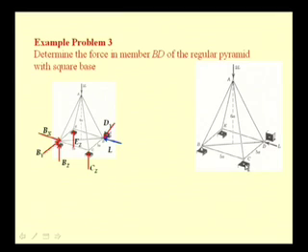And at C we have a slender vertical rod, thereby the member can only support a vertical reaction and thus offers only a vertical component of reaction Cz.